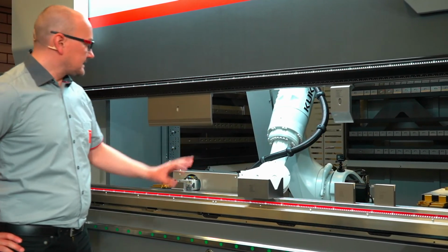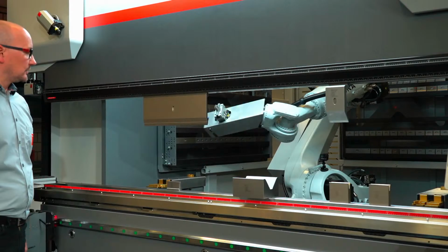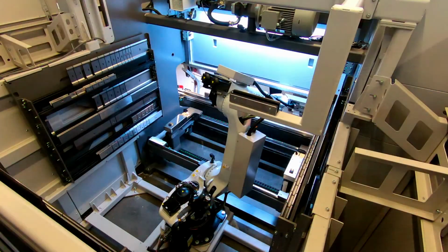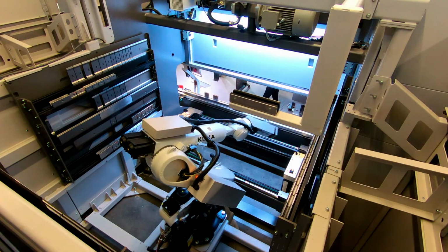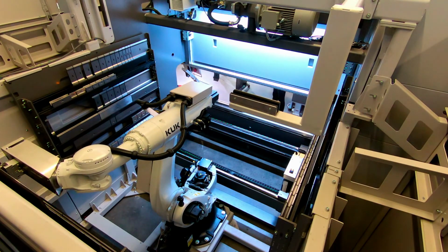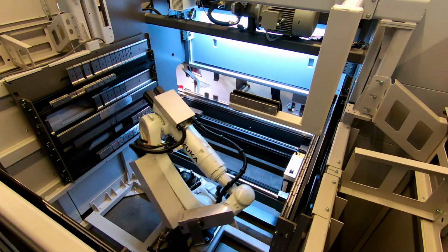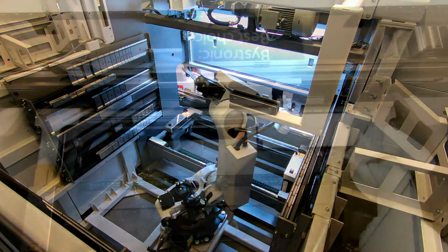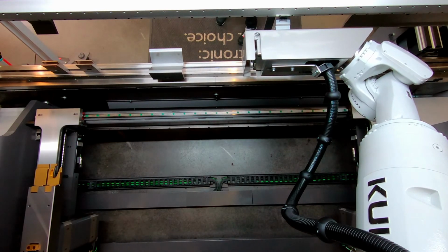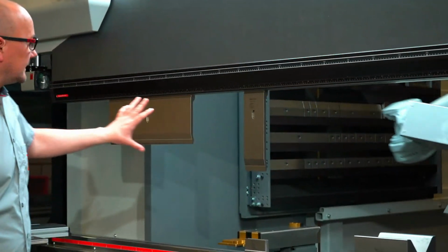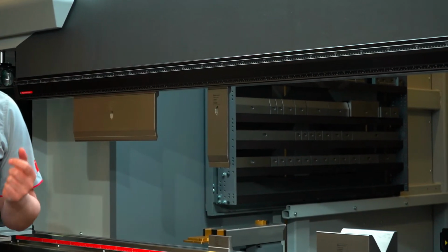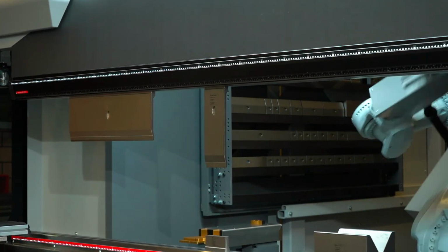And this is the reason why, for the bigger tools, we have a little bit smaller segmentation lengths. For all the other tools, we can have 550 millimeters. Then there is also the handling time, if you have a 3 or 4 meter machine, really, really short. For the top tools it is also interesting. We can have longer tools. The standard ones are 250 millimeters, and you can handle up to 350 millimeter top tools.